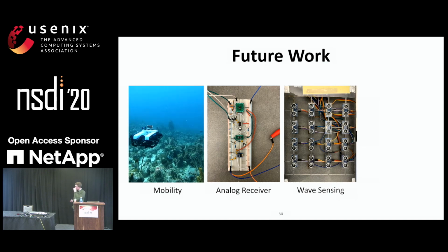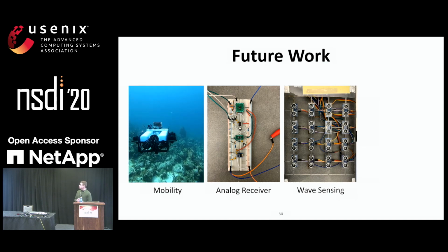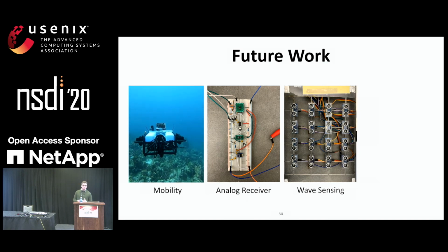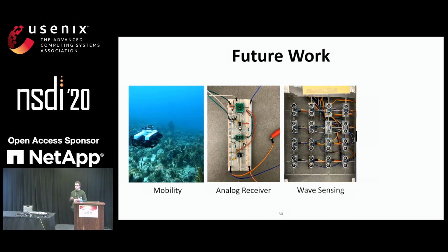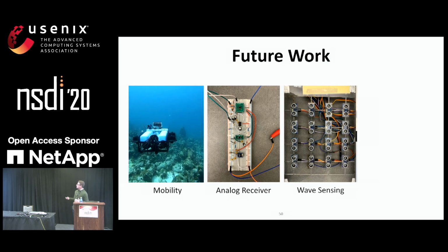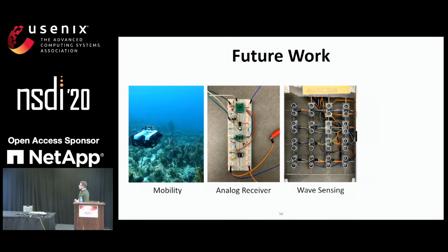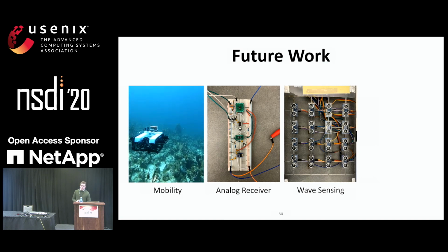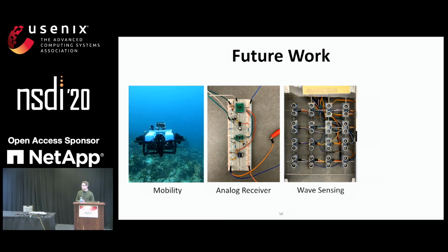Wave sensing. As I mentioned before, we do have a method of reducing that latency. However, this does assume that the wave is periodic and has a dominant fixed frequency, although our method does adapt that frequency depending on the historical data. However, we would like to consider alternative ultrasonic sensors that have variable frequencies, for instance. We can do frequency division multiplexing, and also look at sensors that have tunable powers and beam angles to test the differences for our sensing range.